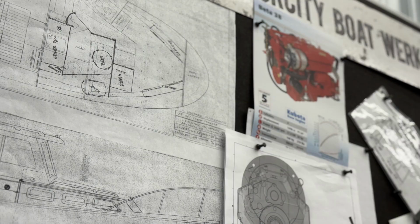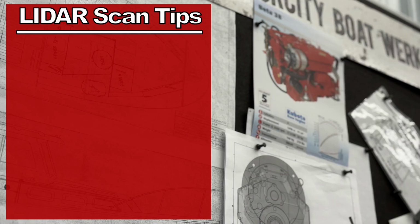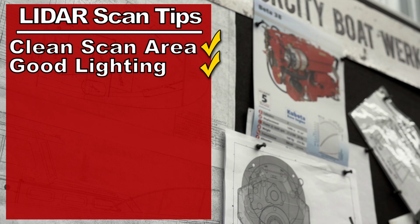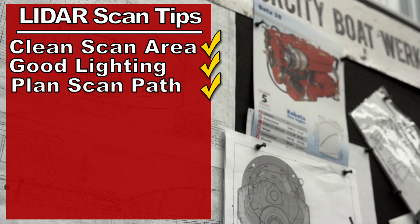From all this experimenting, there are a couple lessons I've learned trying to get a good LiDAR scan. The first one is that you really have to clean and prep your area ahead of time. Remove anything that's reflective, clear away any kind of background clutter. Have good light inside the space where you're going to be working. It helped to have a small floodlight going inside the engine compartment. Plan out your scan before you ever get started. Come up with a path that you're going to take, whether you're going to work from the top down or the bottom up, left to right. You need to know all that ahead of time so everything is very fluid.